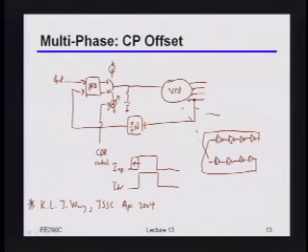Yeah, okay, so the real trick is that you can't really tell the difference between hacking on this and just changing the phase of the reference. Effectively the transfer function you're going through is the same transfer function experienced by the reference. So to the extent that this loop bandwidth is pretty high in comparison to your CDR loop, it doesn't make a big difference. Now you're absolutely right that if I wanted a very high CDR loop bandwidth, then this would be a problem, because it introduces additional filtering and phase shift and so on into my CDR loop. Does this make sense to people?